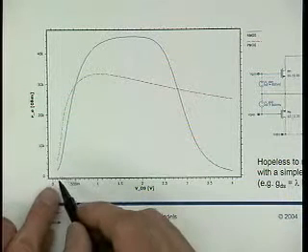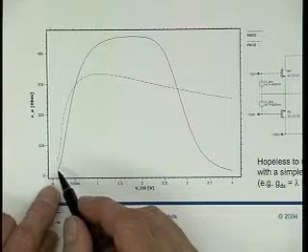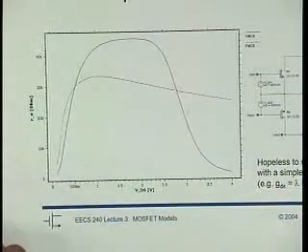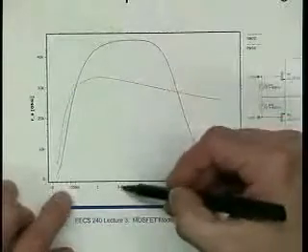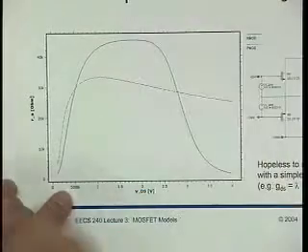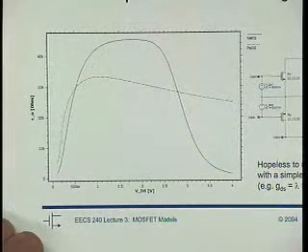similar. R-out indeed is very low in the triode region. Well, no big surprise, and then it shoots way up. It's not exactly a flat, constant thing in saturation. Also, the transition region, never mind here. This is 1.5 volts, right? When we finally reach this peak. And then, interesting enough, in particular for the NMOS device, it starts rolling off again.